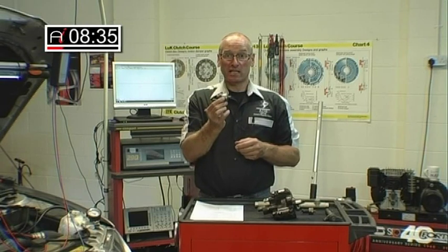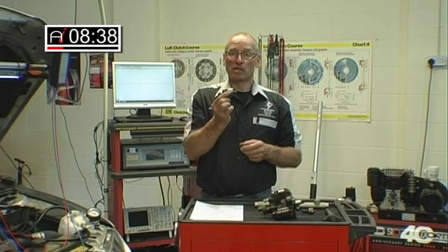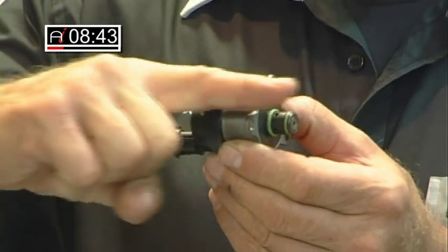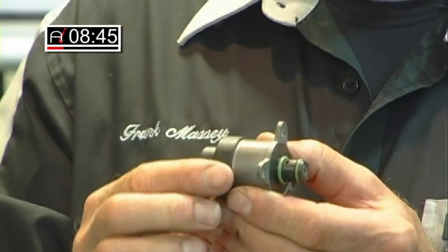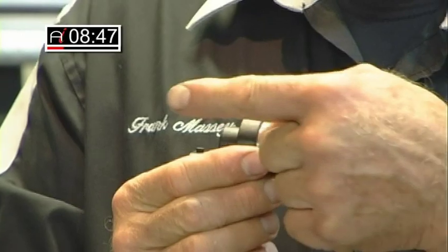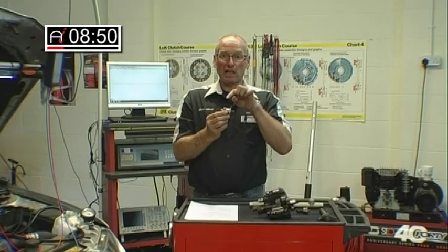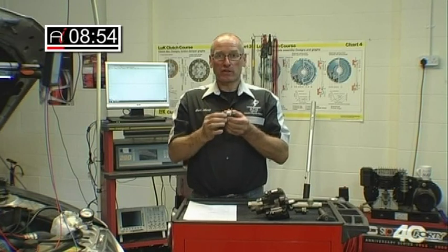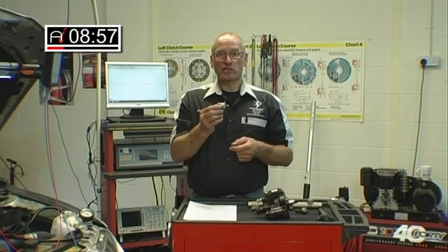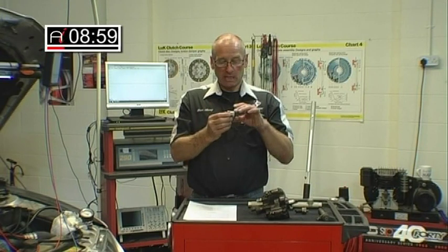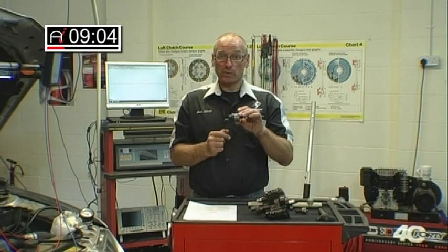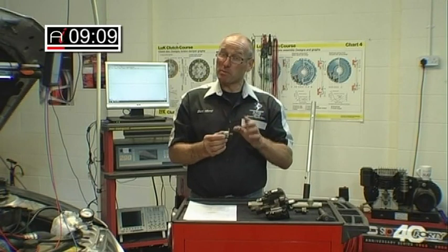So by restricting the escape passage or spill passage, pressure will increase. So you will increase pressure by driving this device in. You will release pressure by allowing the device to open more freely. So you apply more current to this to drive it in, pressure increase, remove current to reduce the pressure in the rail. This is controlled by duty, and that's controlled by the ECU, and we're going to monitor the duty on that valve electronically. It can also be monitored serially.